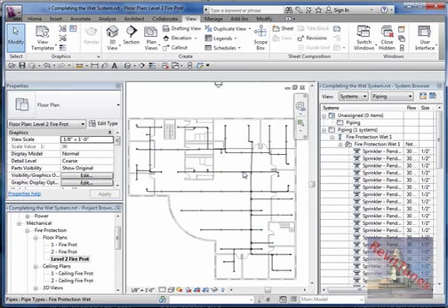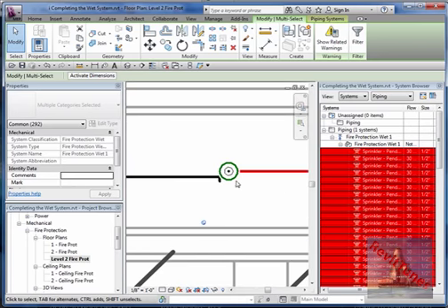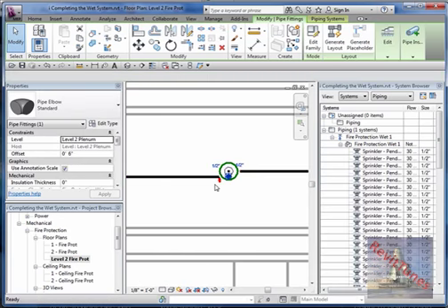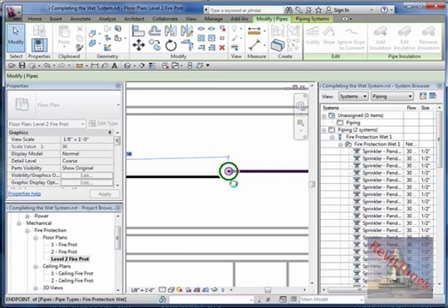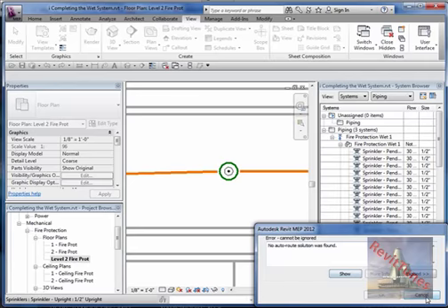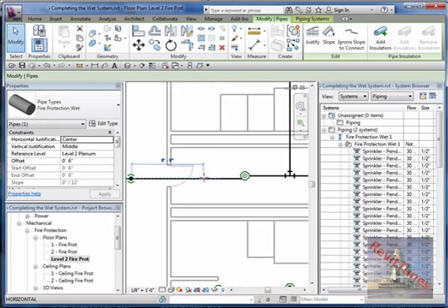So now if you put your mouse on the tab, don't click, and hit the small tab 3 times, and then you click, it tells you what is connected. So right here I have an error. This piece is disconnected somehow. So what I want to do, I'm going to delete the elbow, and it needs a branch. It needs a branch to connect this.